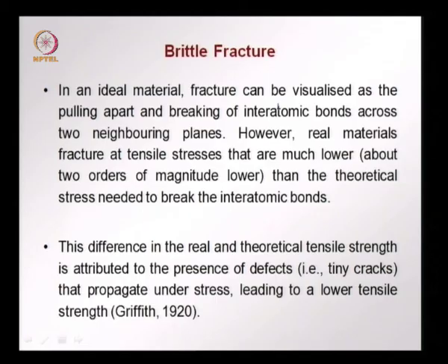The theoretical stress is about 2 orders higher than the actual failure under fracture. This difference was attributed by Griffith in the 1920s to the presence of defects or tiny cracks which always occur in different materials.